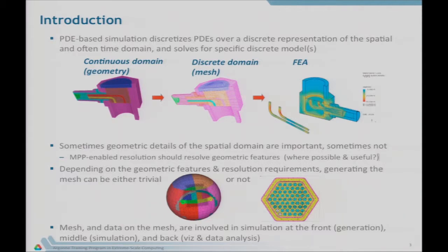So generating the mesh sometimes isn't a straightforward thing because oftentimes you have to go clean up the geometric model or take details out. I usually say that if you're doing massively parallel processing, generating meshes that are very large and very finely resolved, you usually want to resolve the geometric details on that same degree of resolution, but really it depends on what kind of analysis you're doing.